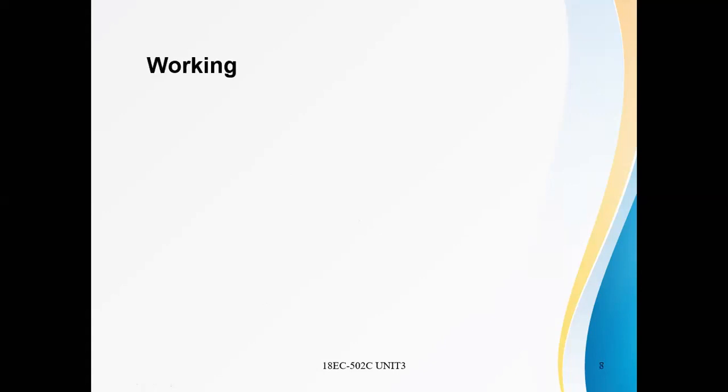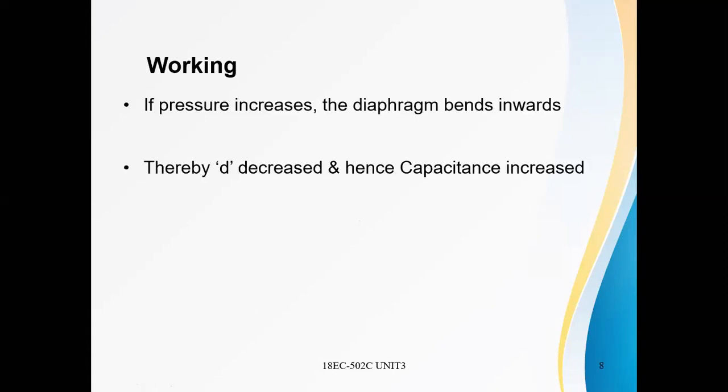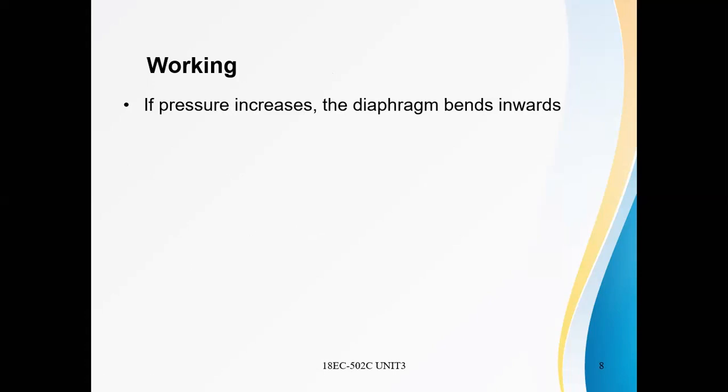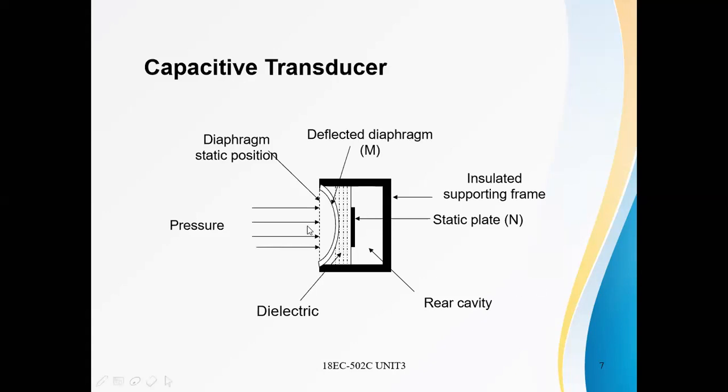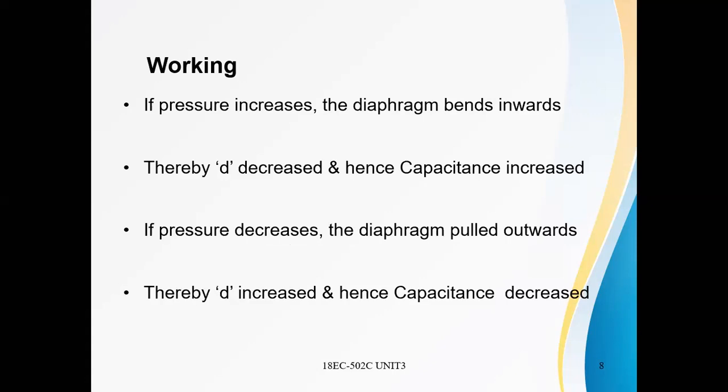Now we will see the working of this capacitive transducer. If the applied pressure increases, this pressure bends the diaphragm inwards, toward the frame. That means the dielectric medium is reduced, as well as the distance reduces.